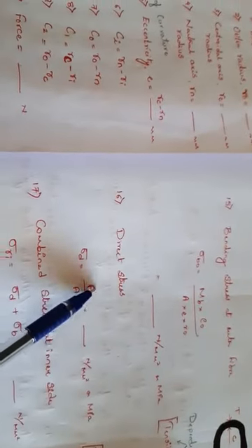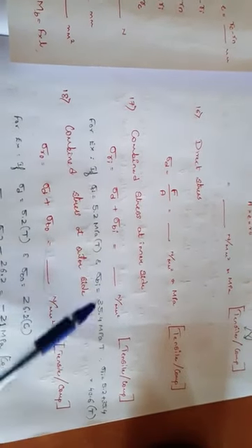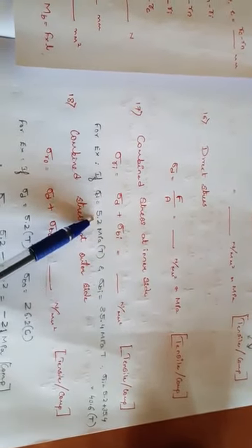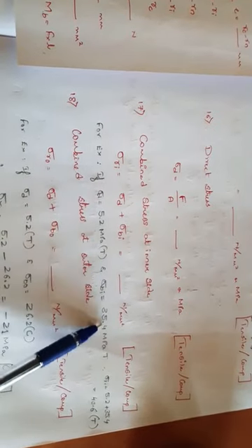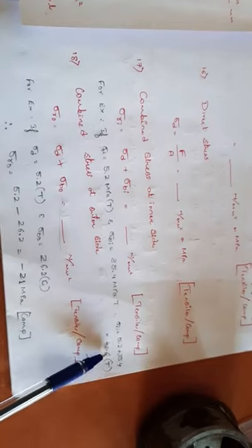So direct stress is F by A. This also is tensile or compressive, depending on the load. So the combined stress at the inner side, sigma Ri, is sigma D plus sigma Bi. It may be tensile or compressive. For example, if sigma D is 5.2 tensile and sigma Bi is 3.4 tensile, then both can be directly added. So we get the answer as positive, that's tensile.